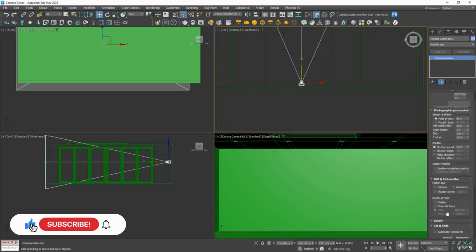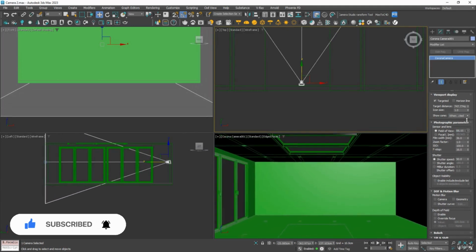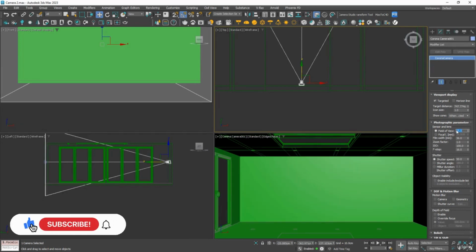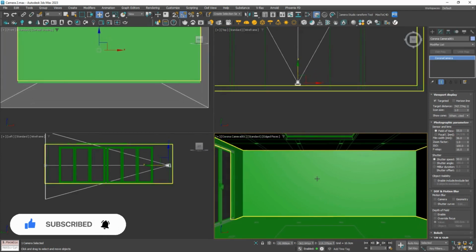And we can also go up to our field of view and we can turn that up, and notice if I pull that up, you can see more of the room. It can be tempting to do something like this, but really try and keep it as realistic as possible. I think when these wider views, they start looking a little bit unrealistic. So I'm going to put, say, 55 in here. And then using the middle mouse button, you can start panning around and just position your camera how you like it. We can change this later, so it's not set in stone, but that's how you can set up your camera.